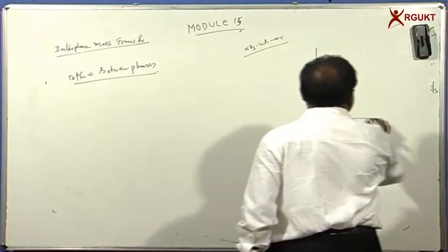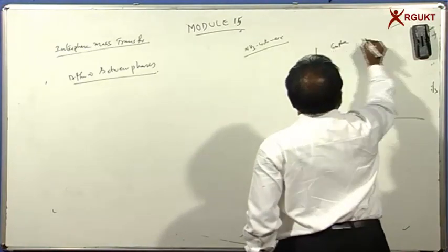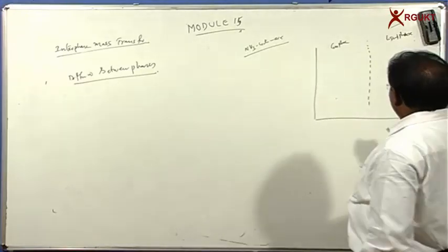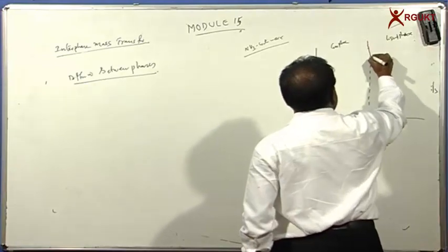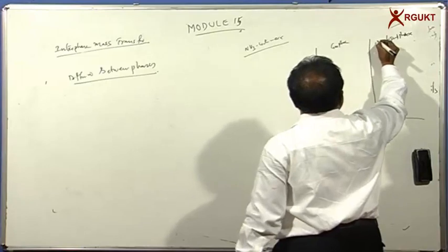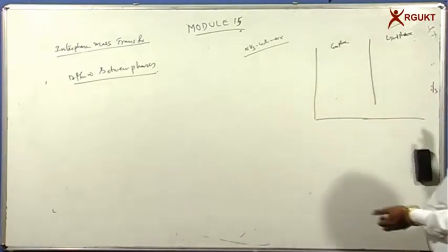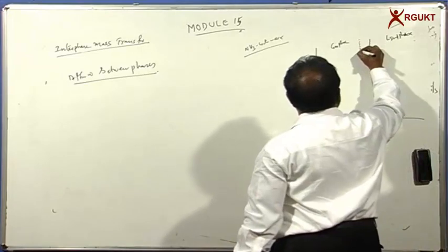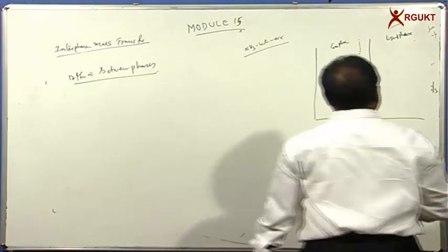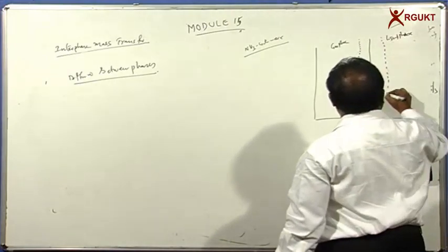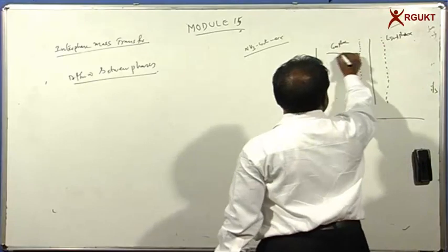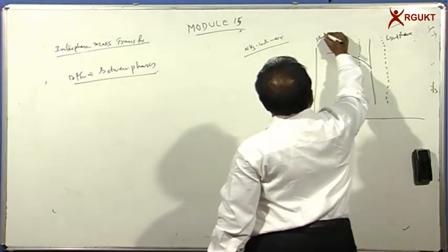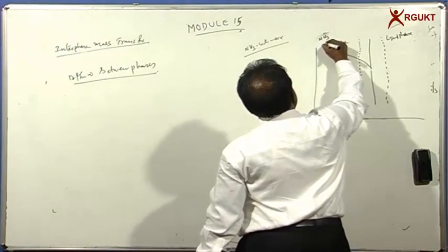Maybe we can say this is the gas phase and this is the liquid phase. So now here we have an interface. Maybe I can draw a thick solid line for the interface. At the interface, on one side we have the gas phase, on the other side we have the liquid phase, and in between there is the formation of the interface. Now we can assume that there is a film on the gas side and a film on the liquid side. And there is a concentration profile, where we have a solute that is nothing but ammonia, and here we have air.